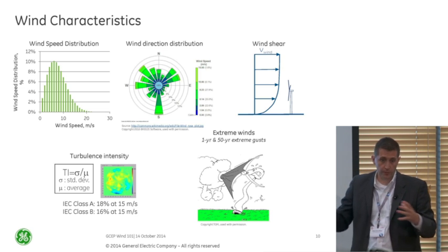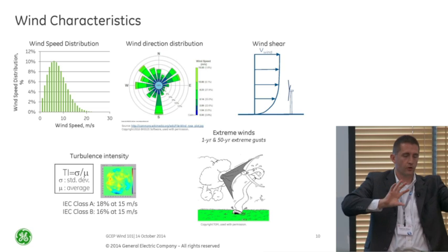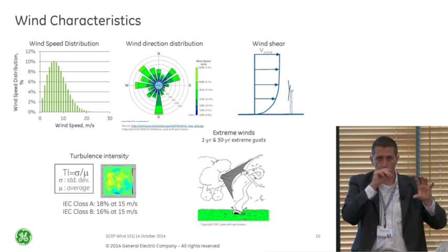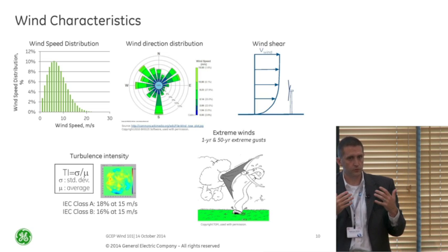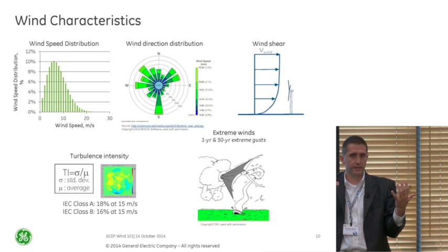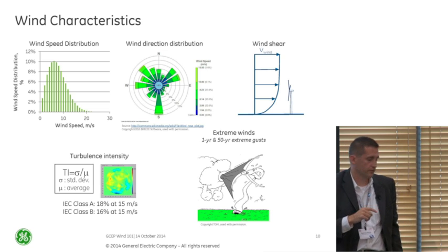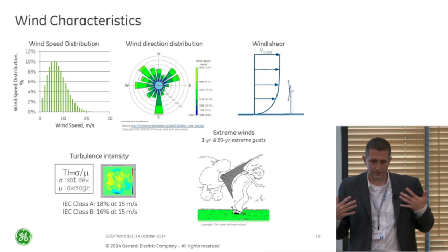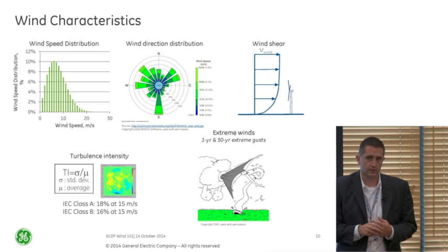We also look at how turbulent the wind is. Remember, it's not this nice smooth field of wind coming in. There's different patches that are going different speeds, especially when I have something as big as the rotor I have. So you're seeing a lot of different turbulence. You need to factor that in, not necessarily for the performance of the wind turbine to some extent, but really for the loads impact, right? This blade might be getting hit with a lot more wind than something up here, and it might be shifting around quite a bit as it moves across different time variations. And then obviously, everyone thinks about, if I need to design this thing, I need to make sure it doesn't fall over or break when I have a high wind event. So that's really important too.